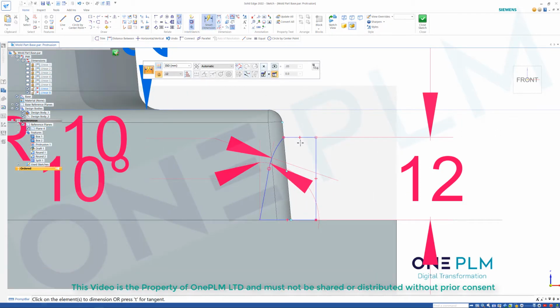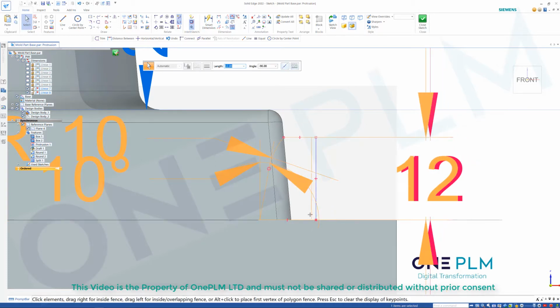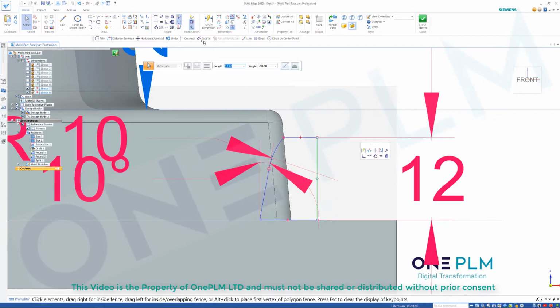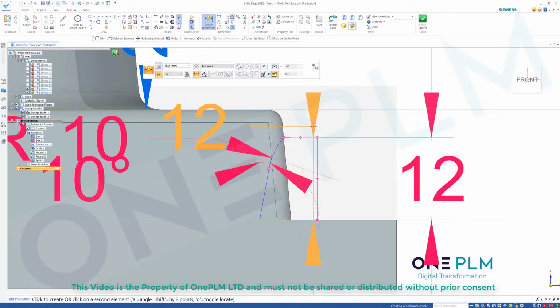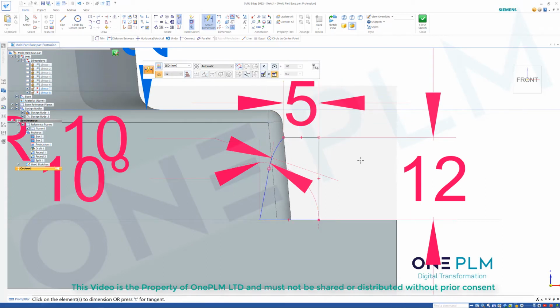So we've got most of our sizes on here. When we're looking at fully defining sketches, I kind of like just clicking on the profiles and dragging that and seeing what's what on there. So we can clearly see that that line obviously is giving us that issue on there. So if I go and do 5 on there, that's good.